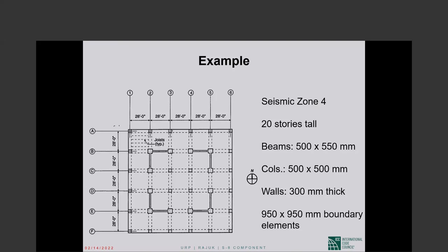Okay, so the coupled shear wall will take the place of an isolated shear wall in a building frame system. You can use it, but only in conjunction with 100% gravity force resisting moment frames.